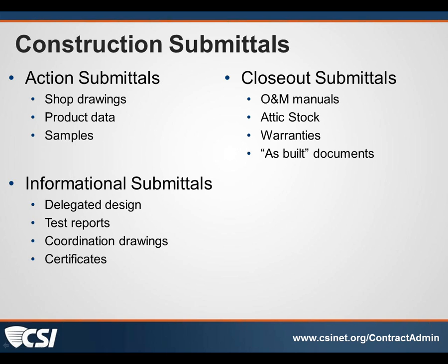RFIs are requests for information or requests for interpretation from the contractor. That is not a submittal, which is again, when the contractor is submitting documentation to show how they intend to comply with the requirements of the contract documents.